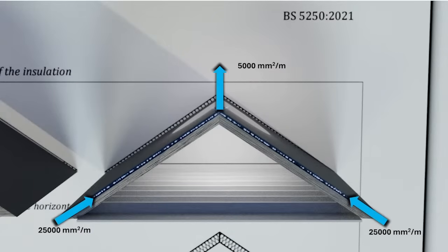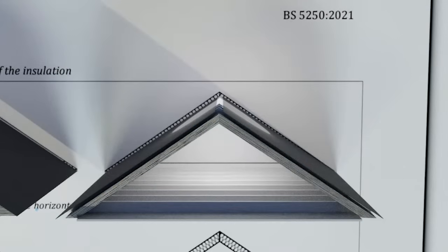Voids and openings should be arranged such that ventilation airflow can pass across the entire roof, taking into account any obstructions like dormers or fire break walls that are present. So in practice, additional ventilation openings like slate or tile vents may be needed to ensure this. For roofs with type LR underlays, ventilation can usually be omitted provided the outer covering of the roof is air permeable. We'll look into air permeability of both underlays and outer coverings in more detail later in the CPD.